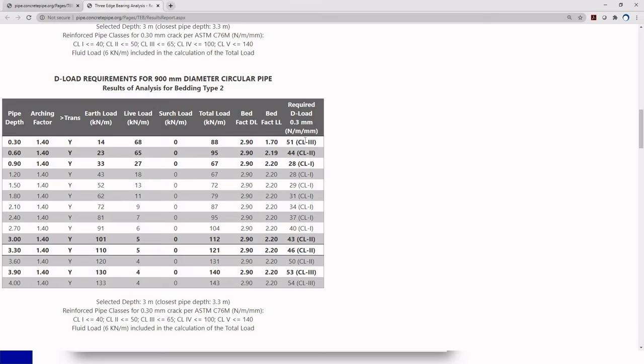The software is always going to highlight each time that you change your strength classification. Remember I showed you that the software will have incremental layers of 30 centimeters going down until 6 meters. As you can see, it only goes up to 4 because I changed that value, so my table doesn't get too long. Maybe I don't need that analysis, but until 4 meters is good.